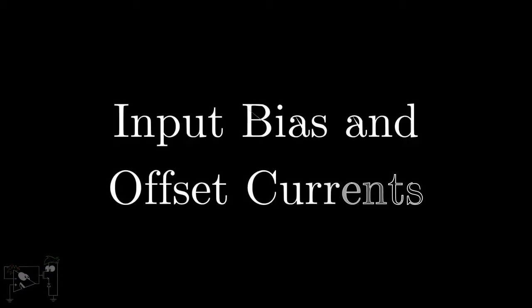In this video, we'll take a look at one of the non-idealities of an op-amp, input bias and offset currents. For an ideal op-amp, the current entering the input terminals of the op-amp is zero. However, for real op-amps, a small current flows through the inputs.